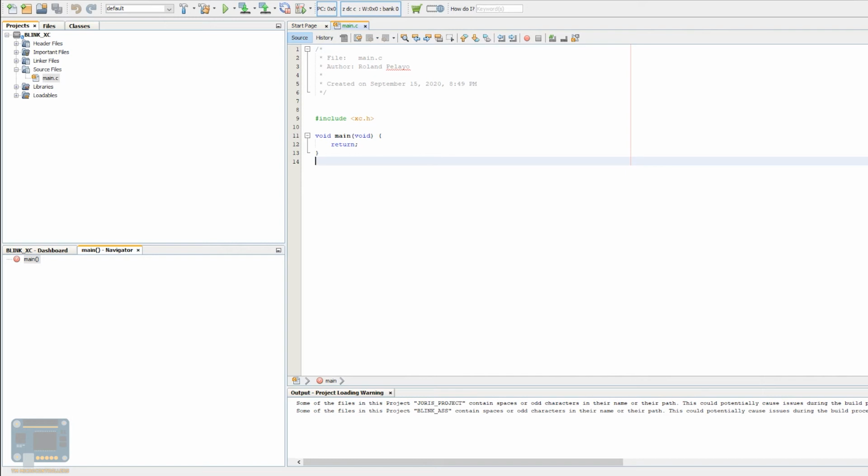Conversely, if you want to make the pin RB0 an input pin, then you must make its corresponding TRISB0 bit high. So basically, that's how you initialize a pin as either an input or output. In code, that would be TRISB0 = 0; of course, don't forget the semicolon. So this is making RB0 an output. Again, if you make this equal to 1 or high, then that would make RB0 an input pin.